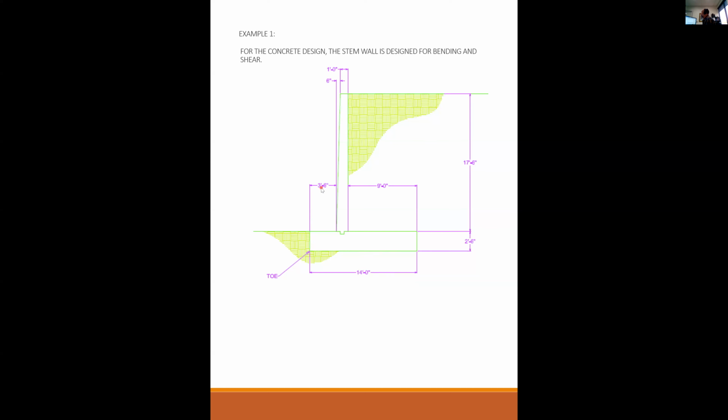The dimensions of the footing locating the wall are 3.5 feet and 9 feet on the back span. This is pretty common that you'll see that the footing is narrower on the front side, much longer on the back side, so that it's like a shovel. It picks up all this extra dirt for stability. The wall itself is 17.5 feet tall, and it goes from 18 inches wide at the base to 12 inches wide at the top.